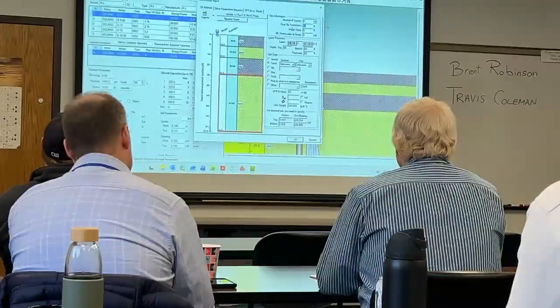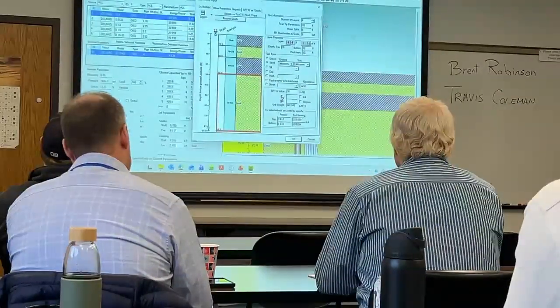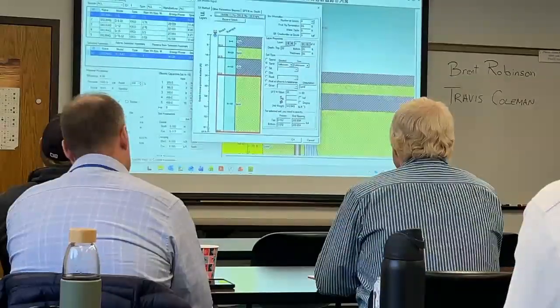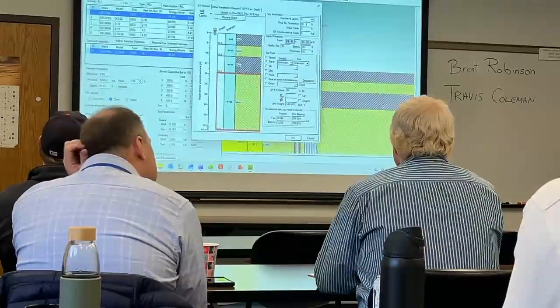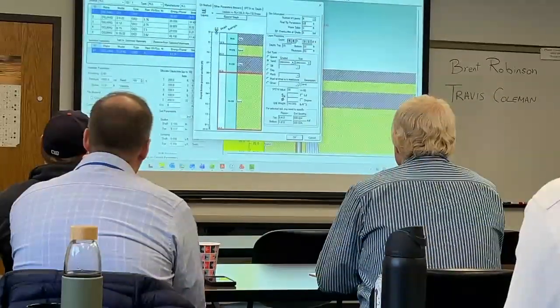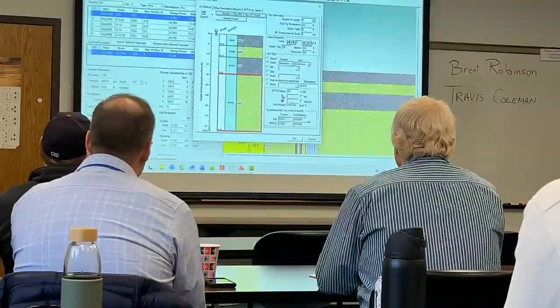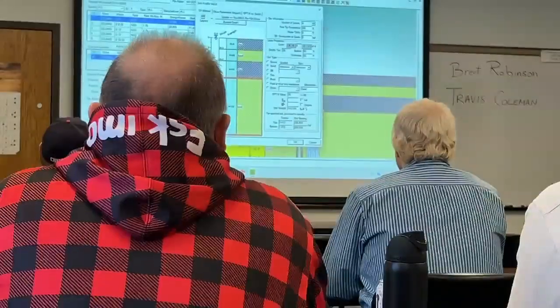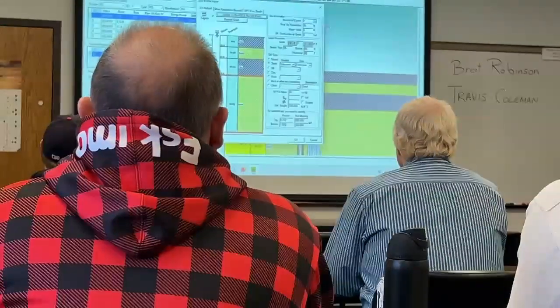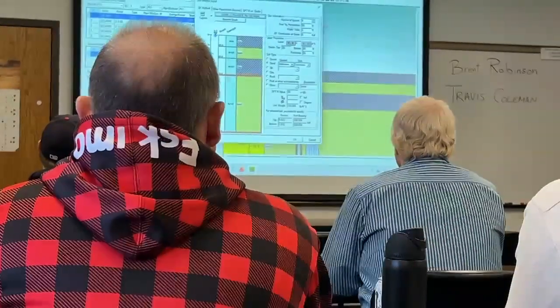So I'm going to keep moving this deeper and deeper until I achieve my required 400 kips. So 65 feet in the ground does not cut it, although it's getting closer. 68 feet, getting close. So 80 feet, I have 406 kips.